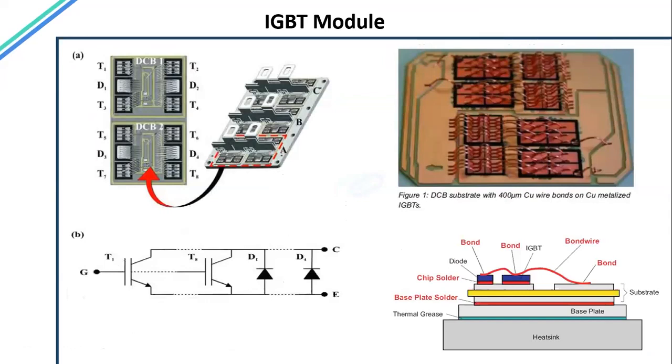So these modules will look like this. You can see the DCB. These are what we call either a module or a brick. These days, some are getting rid of these bond wires, because this is the most critical, delicate element, where it used to fail. So there are different technologies that are being claimed to be getting better and better.